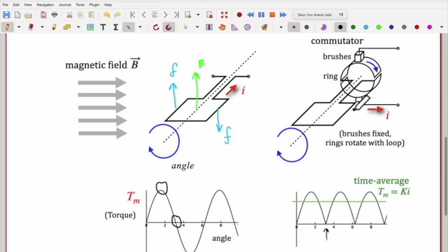And when you do that, suddenly you get positive torque at this point instead of negative torque. And if you're already spinning, if you start it somewhere in here and it starts spinning, you'll pass over this zero torque point and continue spinning like this. And then once you've got that going, you're continually rotating. And with this commutation, you were able to get continuous rotation.